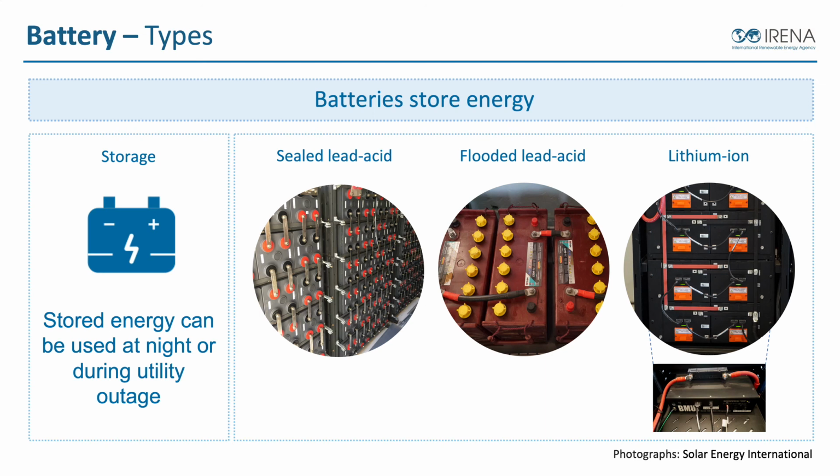In the middle image, we see flooded lead acid. Flooded lead acid is more of the older traditional style of batteries that's been out there for a long time that we've all seen. And these are the type of batteries that have caps that we need to open up and check the water and do internal maintenance by making sure we water the batteries and keeping them all happy throughout their life.